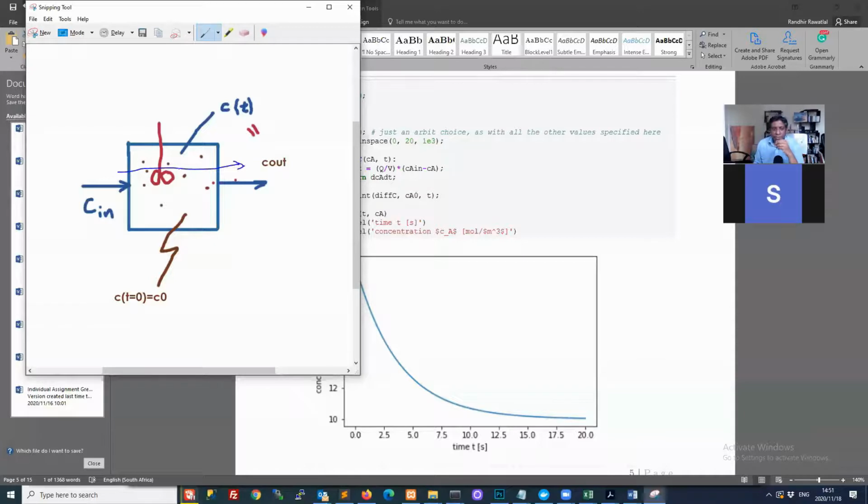So if this is 50 cubic meters, our flow rate here is not 50 cubic meters per microsecond or something. It's not instantaneously replacing all of the fluid in this reactor. It's taking some time. Each element of the fluid is exiting, and sometimes it's not the old fluid, it's part of the new fluid, and so on. We say all this much more professionally in other places, but for right now, we'll say it that way. And so it's slowly being replaced.